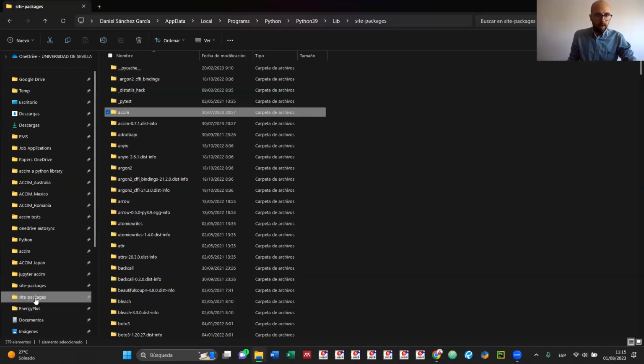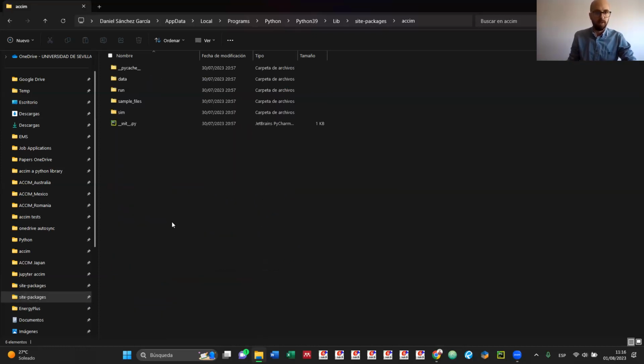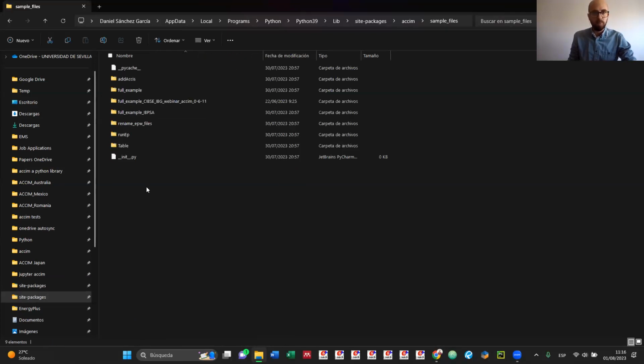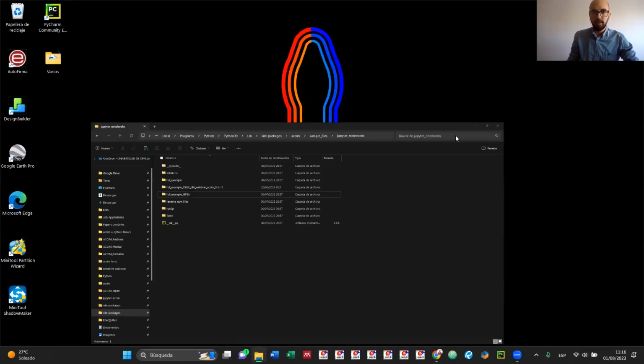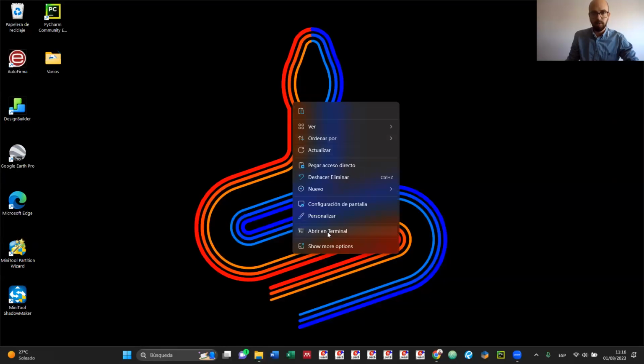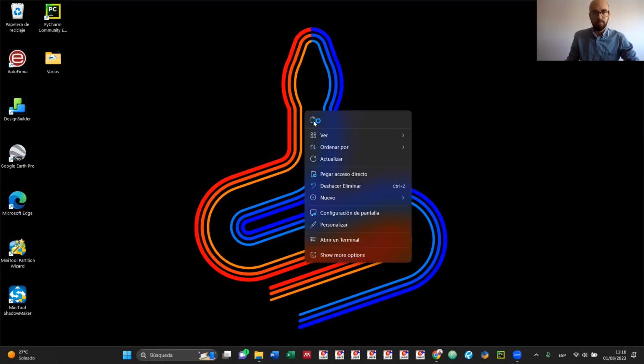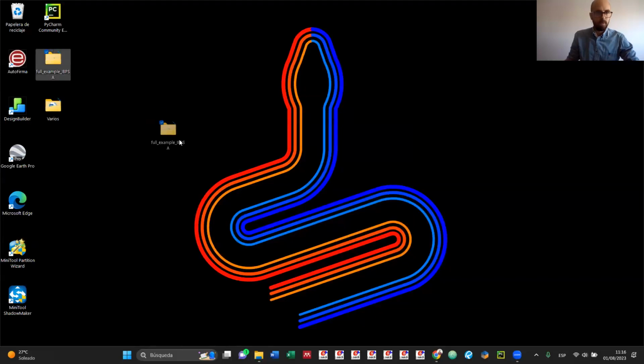Let's open the site-packages of your Python installation folder, and here we have ACCIM. So let's open ACCIM, sample files, Jupyter Notebooks, and here we go. This is the full example for the CIBSE webinar. Let's copy it and paste it somewhere else. Here it is.